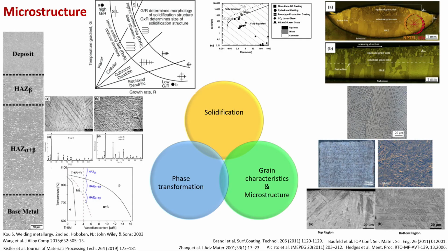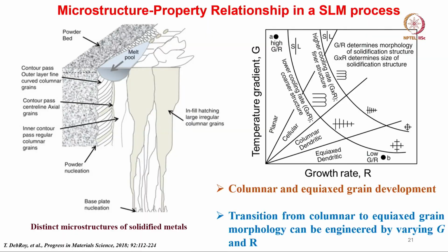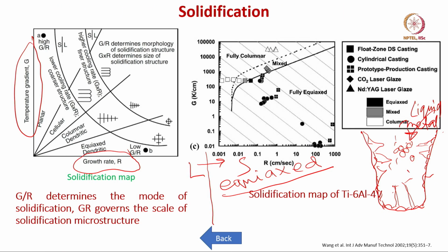smaller sized, finer sized grains. I am just looking at the microstructure which is there. Equiaxed grains are essentially about the sizes of the grains. For example, if you draw a hexagonal array of grains, and you take the center of the grain, and look at 3 different directions of this grain, then you can see that the dimension in 3 different directions is equal. That is why equiaxed means equal dimensions in 3 directions.